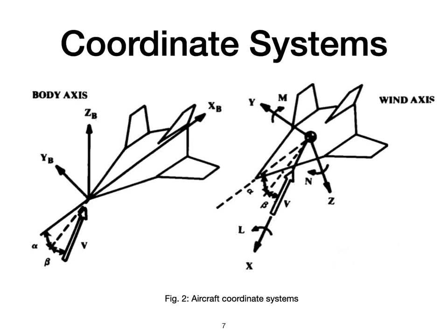The wind axis system solves this problem by orienting the x-axis into the relative wind regardless of the aircraft's angle of attack or sideslip. The aircraft is not fixed to the axis system, so the axis projections of various lengths, such as the distance from the wing MAC to the tail, will vary with different angles of attack or sideslip. This variation in moment arms is usually ignored in stability analysis since the angles are usually small.